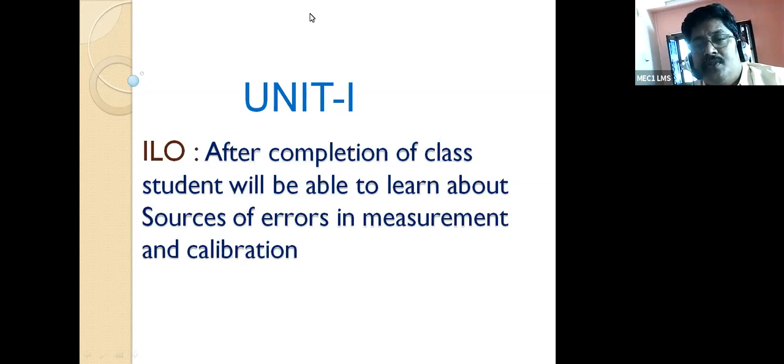In the first stage, we are having a sensor and transducer. Here the sensor detects the variable from the environment. Then the transducer receives the output signal of the sensor and converts it into another form of the signal, a convenient form. Then it enters the intermediate stage.